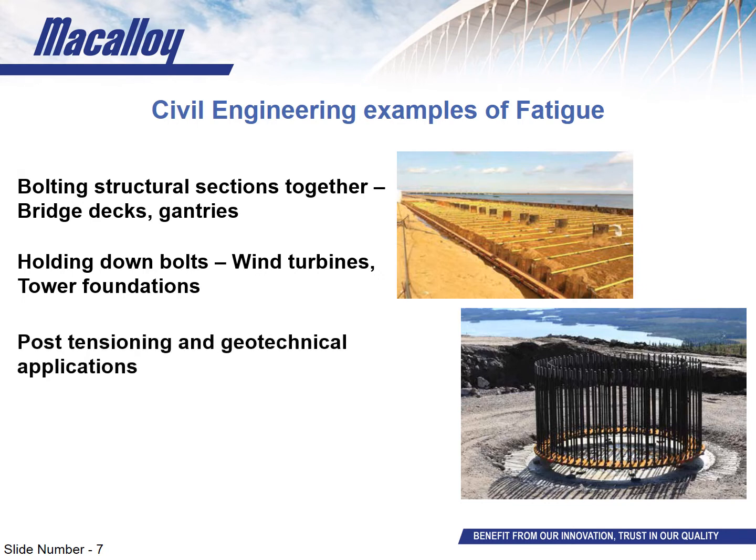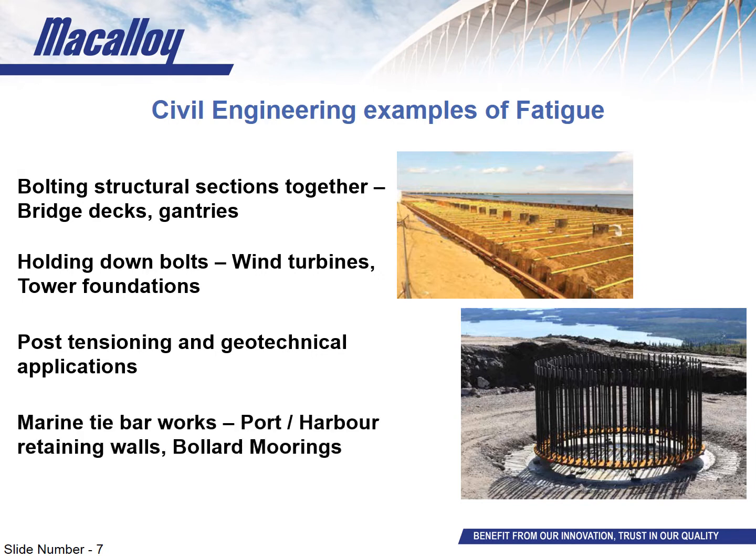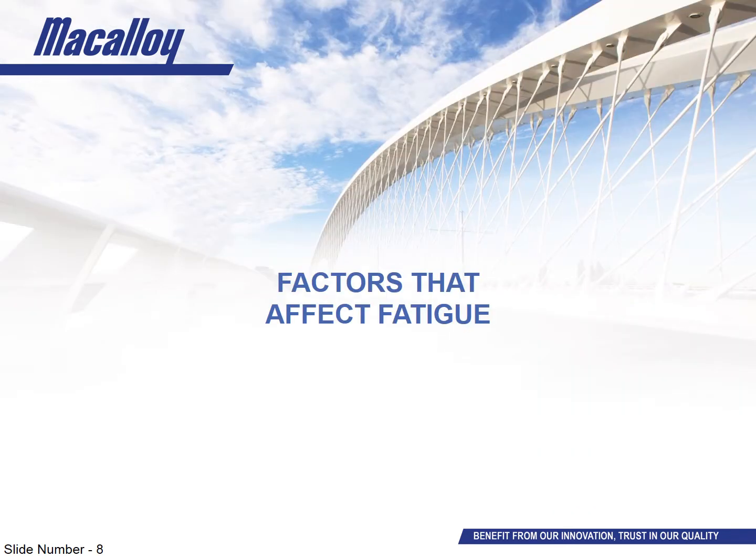Geotechnical works, including rock bolts, soil nails, or post-tensioning bars, are often subjected to a combination of oscillating forces that are minor when only one of them is considered, but when occurring simultaneously, they can amalgamate to a demanding fatigue loading. Finally, applications in ports, such as marine tie bars that are buried under a mound of earth and shipping containers. Now, these can be subjected to fluctuating load and cannot be inspected, so appropriate fatigue allowance has to be put in place. Obviously, these are just examples, and each structure or application should be assessed based on its own conditions or requirements.